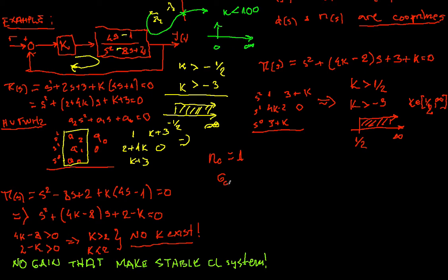What is the first order controller? Now G of c is something that is going to be alpha 1 s plus alpha 0 over s plus beta 0. So this is the first order controller, okay, which allows us to have more parameters, alpha 1, alpha 0 and beta 0, such that we can utilize them and ensure the closed loop system stability. What do we have now? Let's write the P of s in this case.